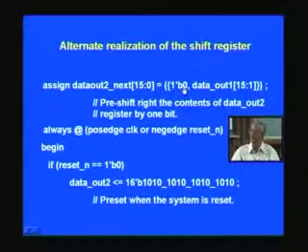Concatenate 0 here, because after right shift, what happens to the MSB is we fill 0 there. So we put a 0 here, and then we separate by a comma. It means this whole thing you should regard as a single 16-bit value, and the first bit we are forcing to 0 by putting it like this, and then follow it by the actual 15 to 1, because after right shift this 15 to 1 will go to the rightmost end.